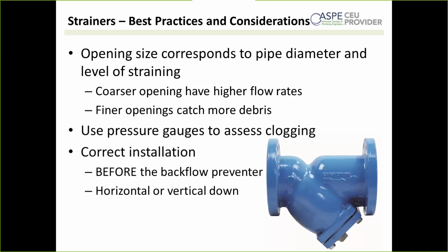It also needs to be installed correctly. First, this means installing it before the backflow preventer. I know this seems obvious, but I've seen people say, hey, you recommended a strainer? I got a strainer and it's downstream of the backflow. A strainer only protects the equipment downstream of the strainer.